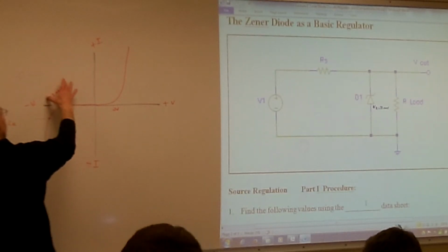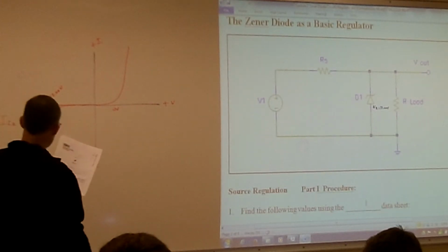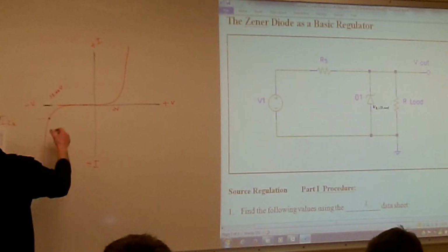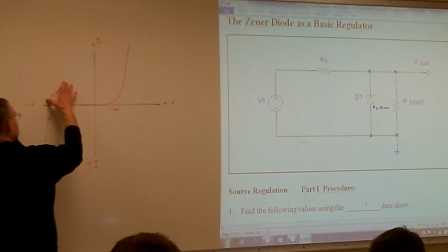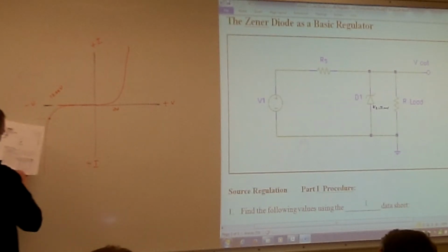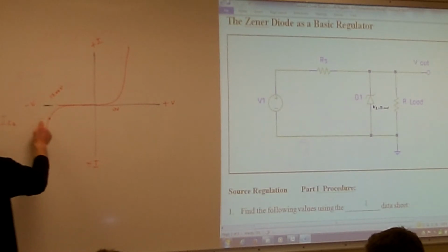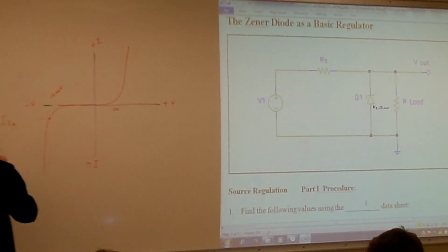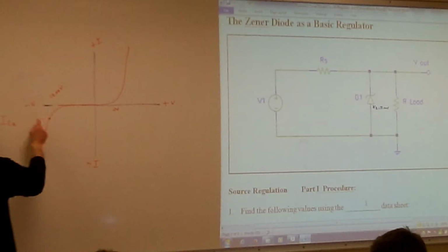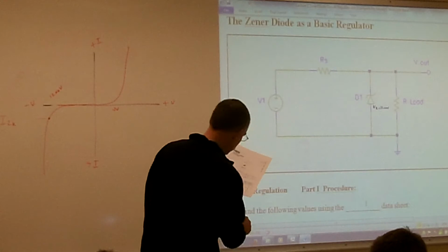This is the actual voltage that they measure, the Zener voltage at our test current. So they're going to make sure they have 21 milliamps of current, and they read what the voltage of the Zener is. Then if you keep scrolling over to the right, it says the IZK is 0.25 milliamps, or 250 microamps. That is this knee current right here. That's the minimum amount of current we have to have on this Zener and still have it maintain regulation.